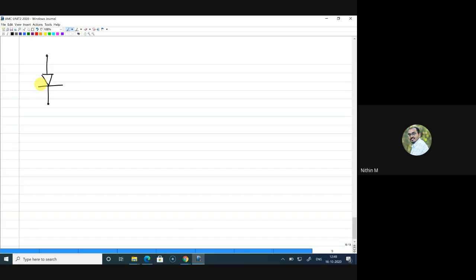All right. Now, for a PN junction, say there is a voltage applied between the terminals, say it is forward voltage VF. Then, for a forward biased PN junction, I can write the diode current ID as, I hope you can recall this expression from your basic electronics, e to the power of VF divided by eta Vt, minus 1. Can I get a response from you whether you are familiar with this expression?